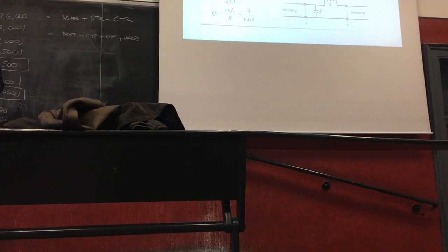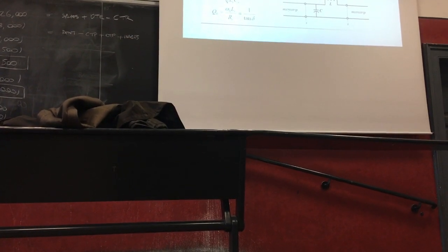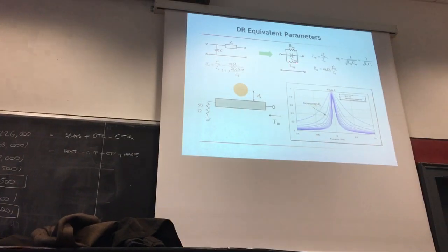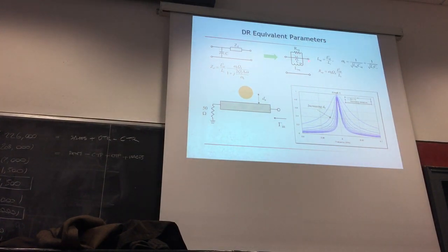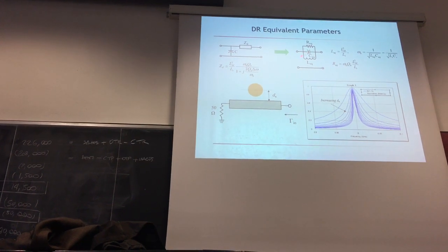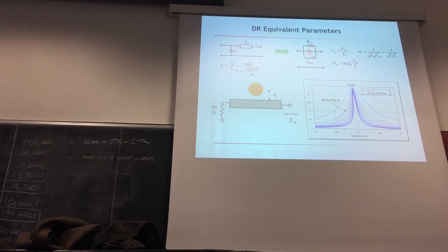With this type of representation for the coupling between the electric resonator and the microstrip, we arrive in the end at a representation where you see that when the electric resonator resonates, we have a shunt resonance circuit. When this resonance circuit resonates, what remains is only this R equivalent, which connects the two sections representing where the coupling happens between the electric resonator and the microstrip.